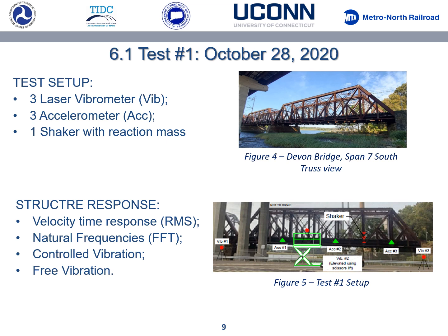Test 1, October 28, 2020. For this particular test, we use 3 laser vibrometers, 3D laser vibrometers, 3 conventional accelerometers, and 1 shaker. All the tests were made on span 7, shown in figure 4, and even the finite element model was made to mimic that particular span.